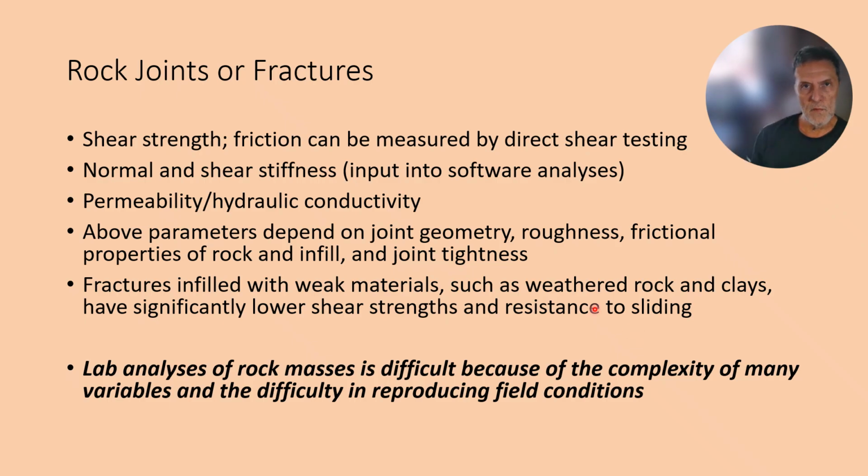Now, in the lab, it's pretty hard to analyze a rock mass just from a small sample. As I've mentioned, a large rock mass's strength properties and other properties are determined by the overall fracturing, the overall density of fractures, number of fractures, how close the fractures are spaced, and whether or not they're rough or have clay, weak clay infillings.